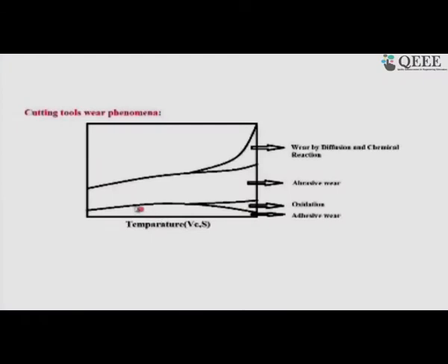But the interesting thing is that as you increase the temperature, or the temperature accelerates and goes up, and this is mostly because of velocity and feed, that we have also noted. So, because of that hardness will fall, that is number one, that may lead to abrasive wear because hardness is falling. Abrasive wear resistance means hardness. However, now comes one new mechanism. It is actually opening the floodgate. It has nothing to do with the hardness of the material, though we have noted that temperature means fall of hardness, but it is not just the hardness.